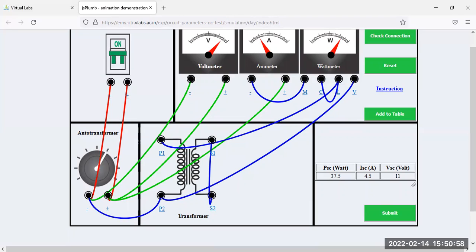So if you put the value on this formula, you will get the value of X equivalent. That means impedance square minus resistance square, you know. So that means the square root of 2.44 whole square minus 1.7 whole square. Okay, if you solve, you will get the value of equivalent reactance. Or otherwise, if you directly submit here, you note down and just calculate simply all the parameters during the short circuit test required. That means the resistance value and reactance value refer to the high voltage side. Okay, otherwise if you put here directly submit, then you will get the parameters of the transformer.